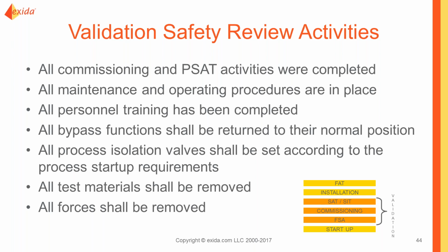the output. So we're going to review that all commissioning and pre-startup activities were completed, maintenance and operating procedures are in place, personnel have been trained, bypass functions are removed and the system is in its normal position. Isolation valves are set in their proper position. All test materials are removed and all forces are removed. And at that point, you're ready for startup.